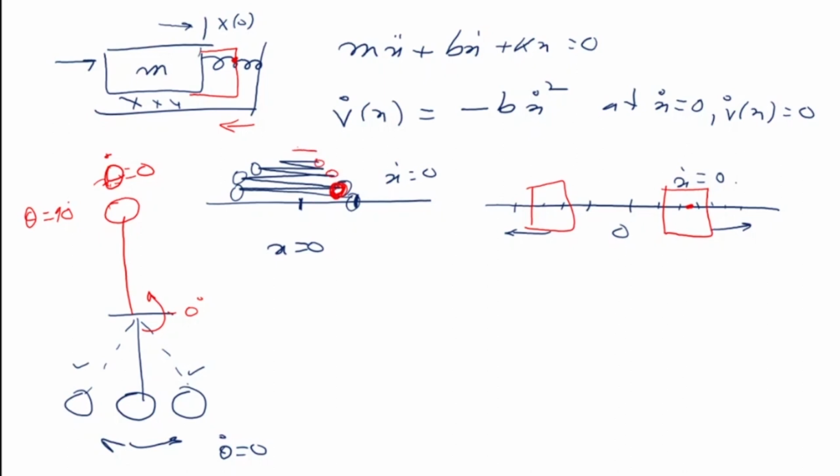So at the end points here, there is an acceleration which is pulling the mass backwards. And at this position, there will be an acceleration in that direction. Because of which, although x dot is equal to 0, the mass is subjected to an acceleration which is going to pull it back again. So it is not a stable point. The mass cannot go and sit there. It will immediately go in the reverse direction. And the only stable point is here at the equilibrium point. We can intuitively understand that this is why it is happening.